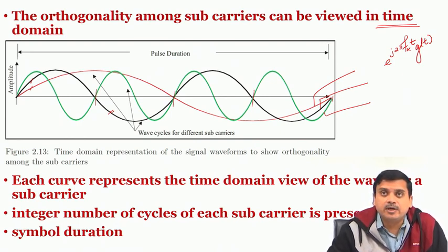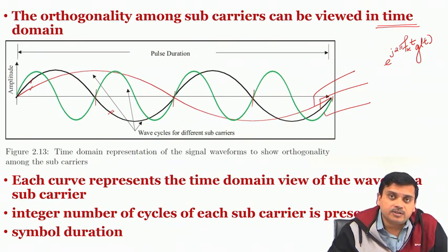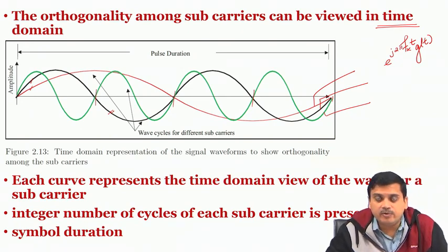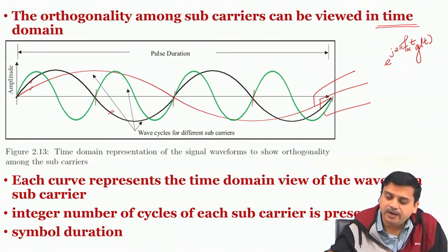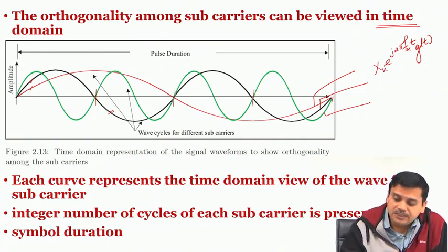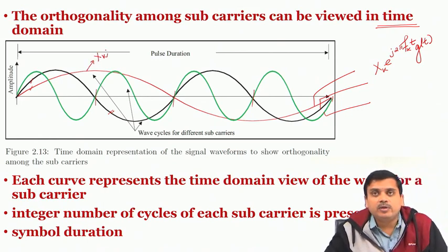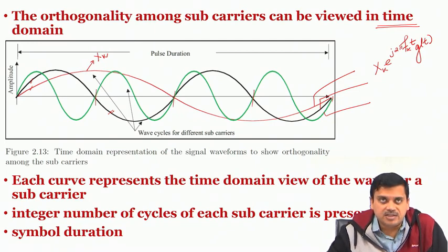when we were discussing, but it was already present when we were discussing the fundamental baseline signal model of M-ary FSK, and we discussed orthogonal M-ary FSK. Then we discussed the OFDM structure in quite a few lectures back, where we said that let this be the foundation on which we will build, and we had x_k in each of the frequencies. That means each of these carriers is going to carry a certain x_k, which will be an amplitude and a phase term.